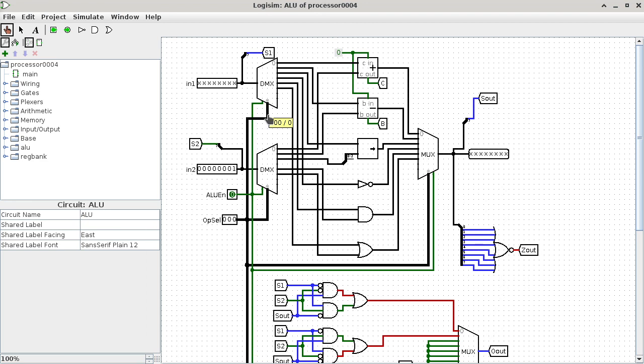That is correct. Okay, so we want the selection to be 001, so that we are telling the demultiplexer to connect the input to output one, and we also want enable to be a one. That would get us the minuend to the subtractor, and then for the subtrahend, it's the same thing except we're doing it with the other input pin, another multiplexer, but same thing.